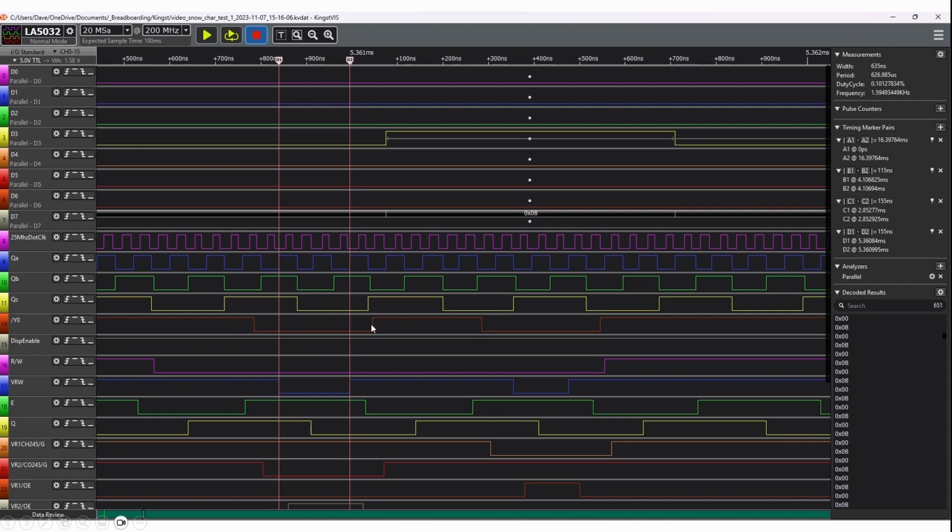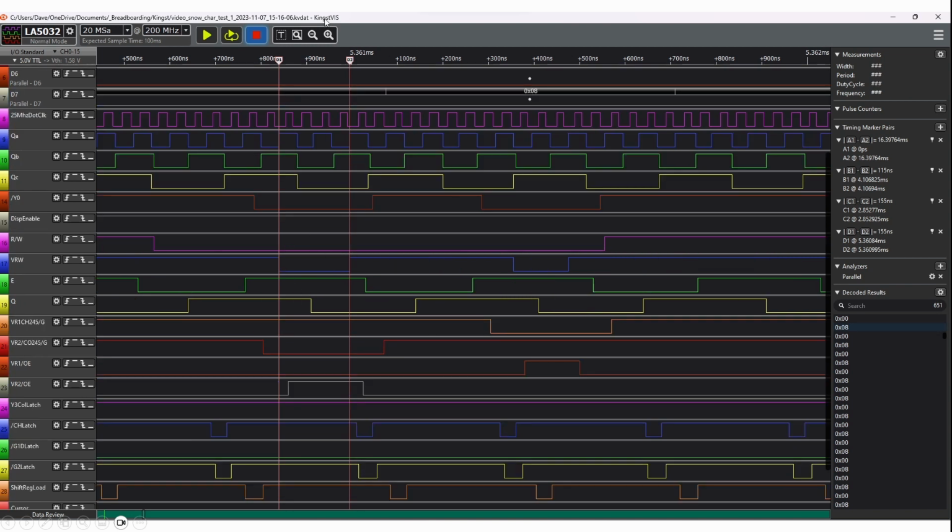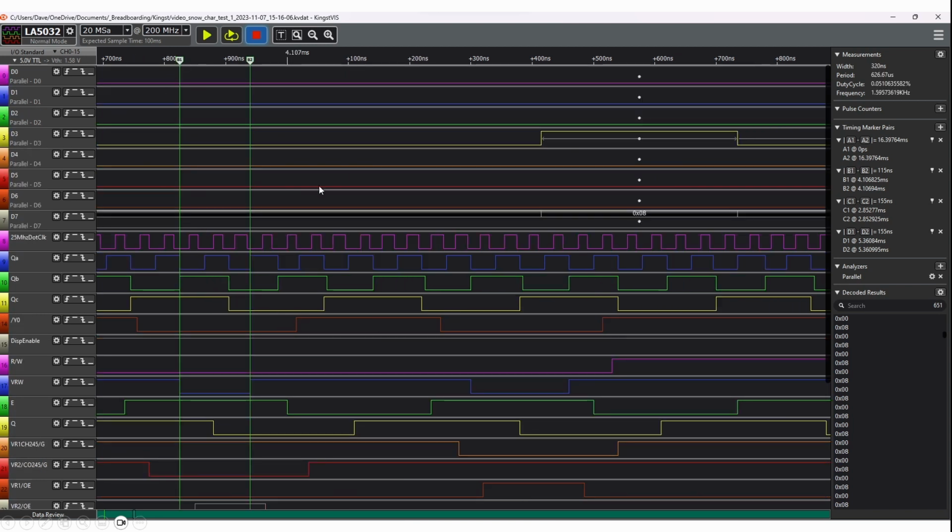If we look at the next one here, just going down to the bottom, you can see this character latch signal, where we're loading the latches to do with the colors and the characters. When the Y0 values overlap with these, that seems to be what's causing the issue here. There are a variety of these signals.